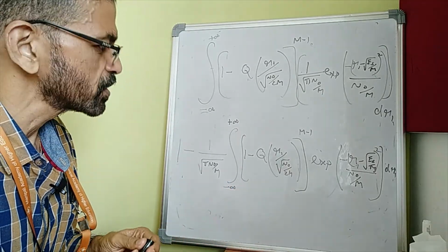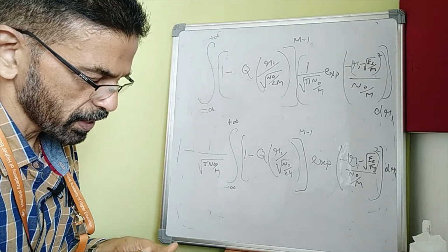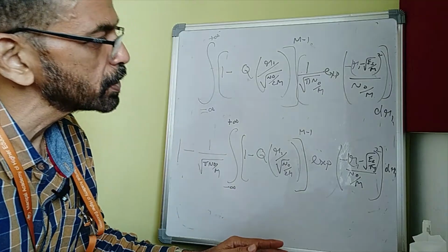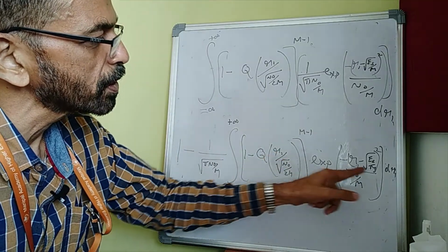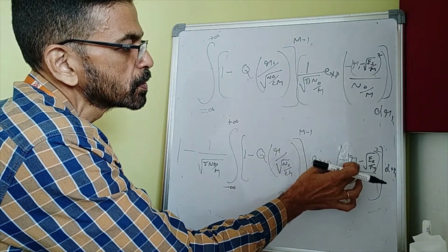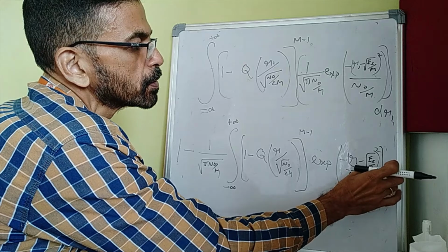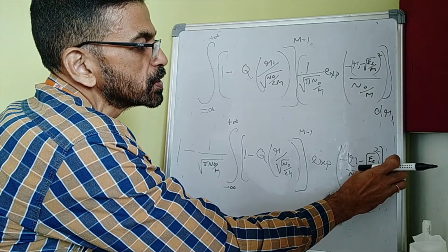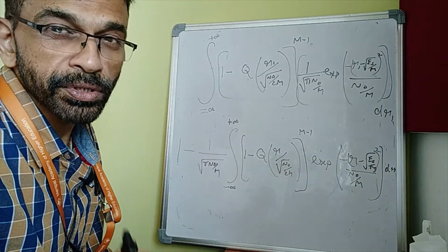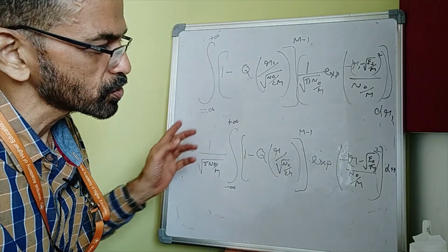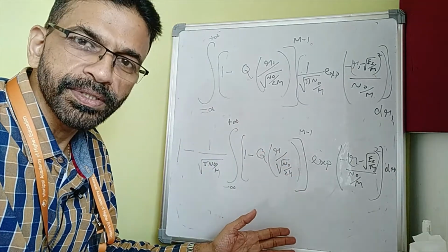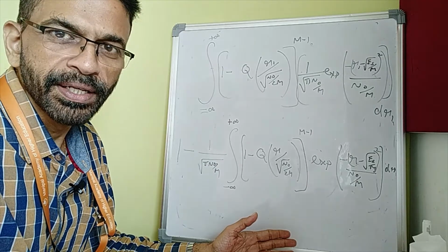And because of these reasons, the average probability of symbol error will be the same as this, which means that we no longer need this qualifier R1 here. We will be better off by dropping this, because we see that it is not just the probability of detecting S0(t) erroneously, this is the probability of detecting any of the symbols or signals erroneously.